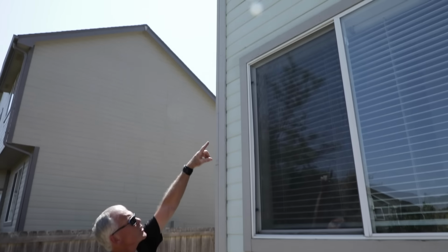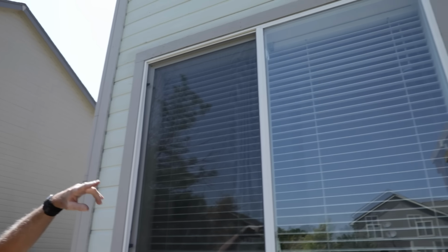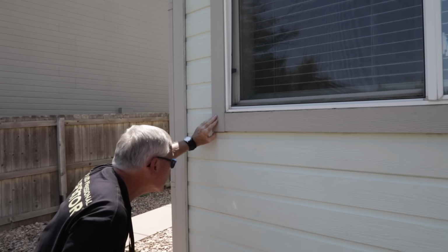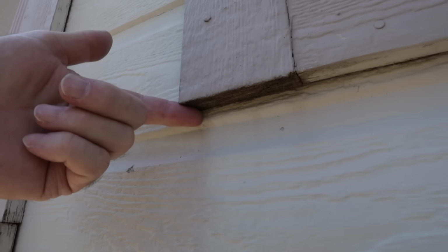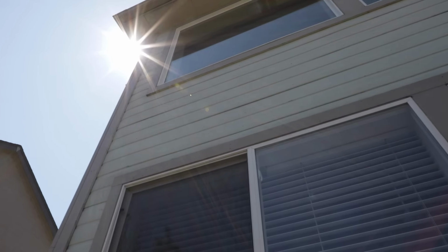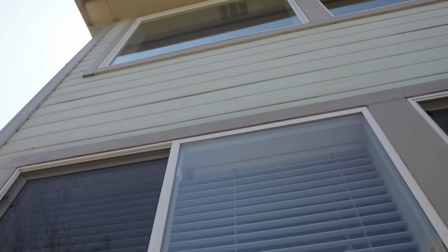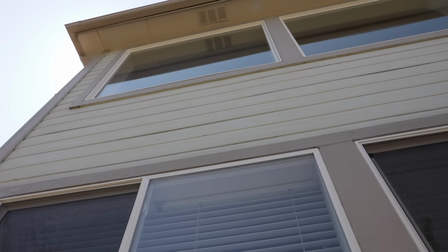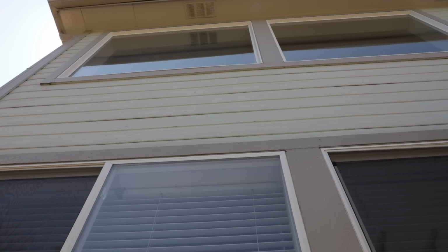I can see our flashing above the windows here. And we want to make sure our trim's in good shape. A little bit of peeling paint here. If you look underneath here in this trim, this trim never got painted at the bottom. So I want to make sure we note that. Up there we see a little bit of water damage at the bottom of that window trim, the bottom corner. It looks like they never painted the bottom of the trim there. So I want to get that in our report.